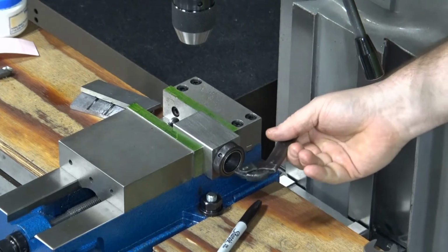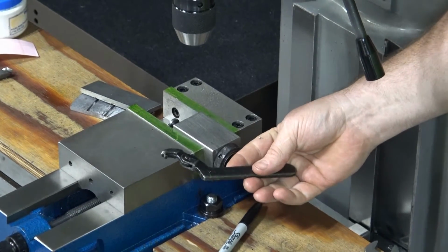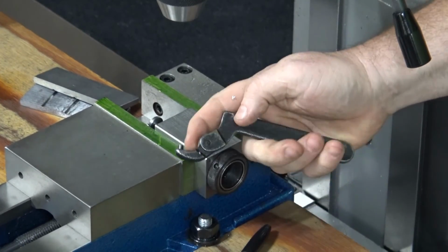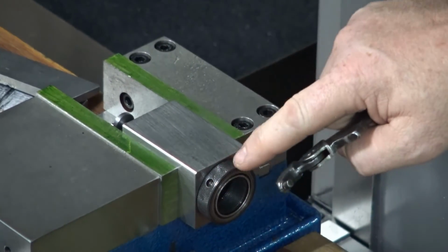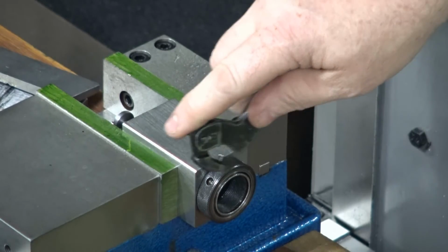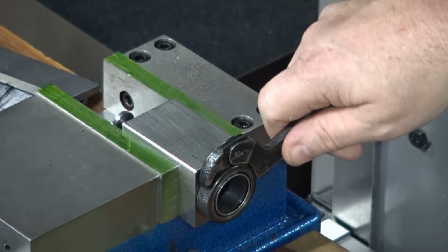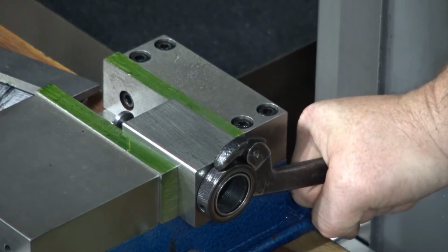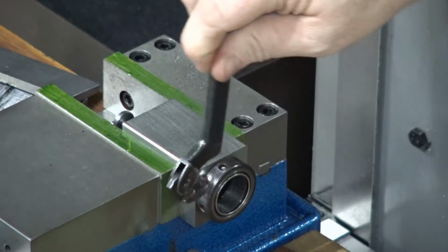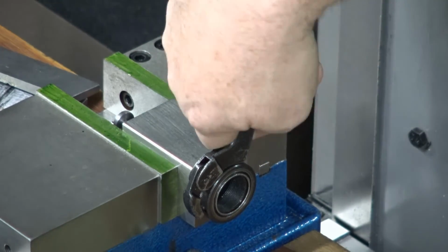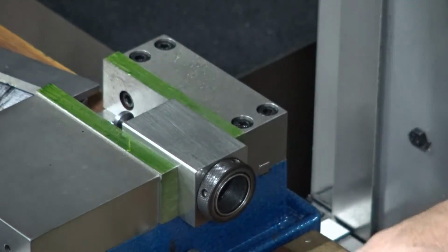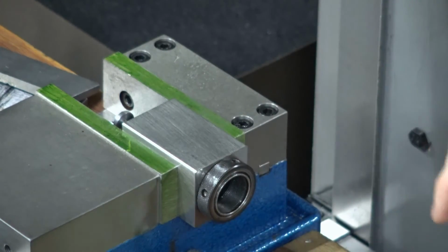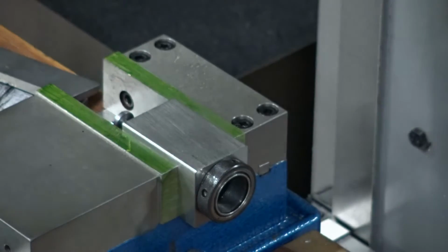And this is a spanner wrench. So this spanner wrench has a round pin on it, and my threaded collar has round holes drilled in it. So if I line that up and I put torque on it, what I've done is I've applied that torque or that pressure, and it allows me to hold on to that round stock much tighter, okay?